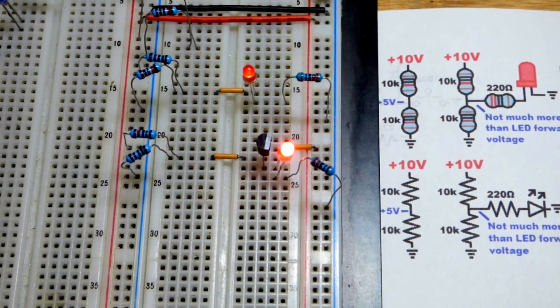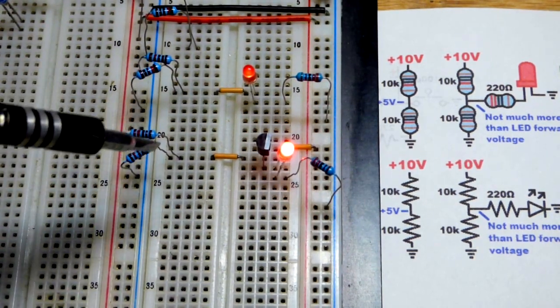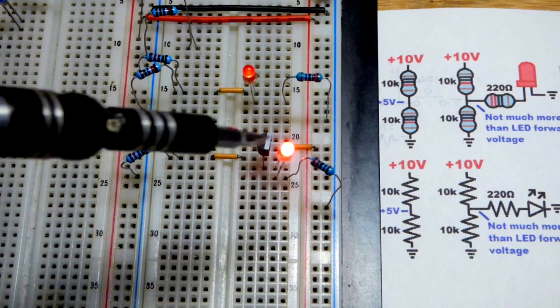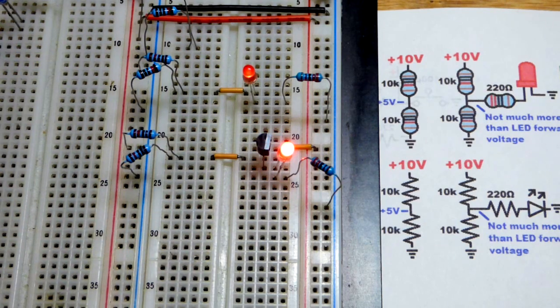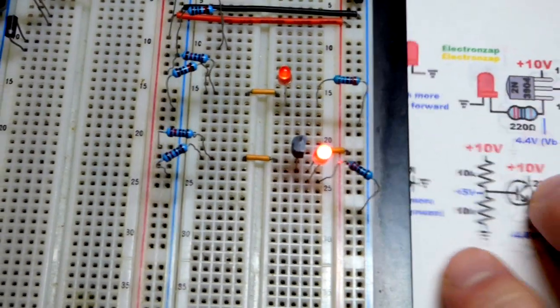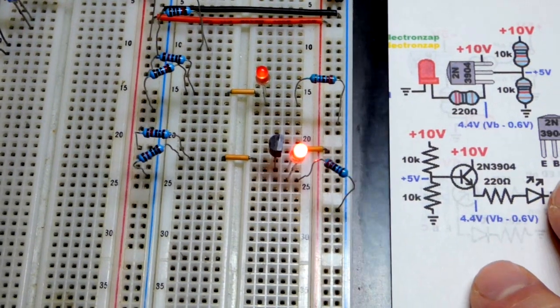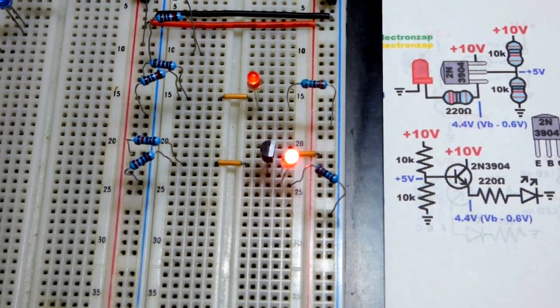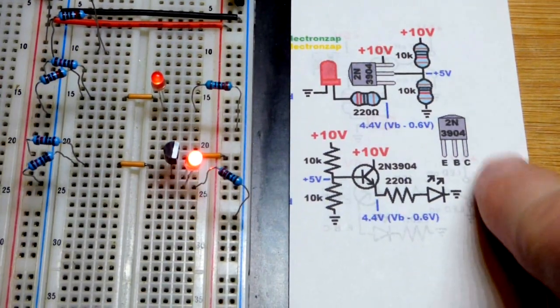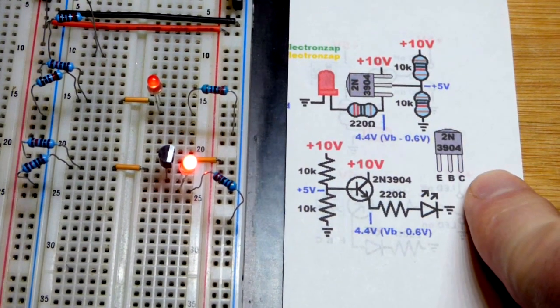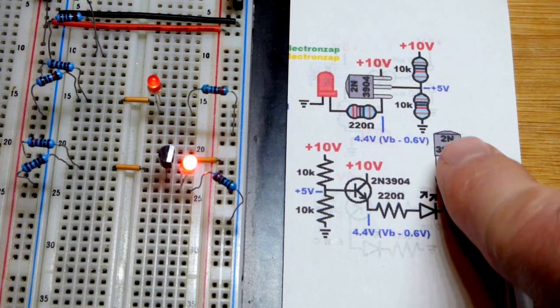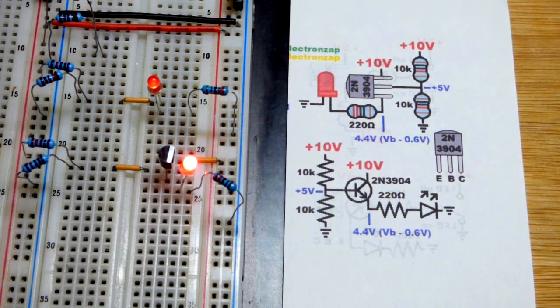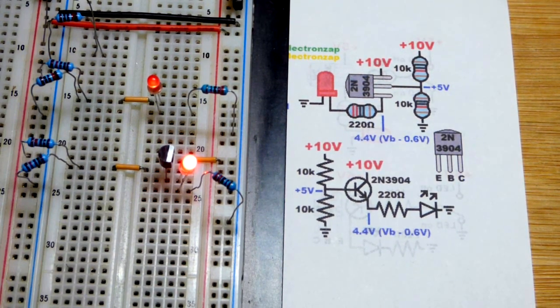So down here we also have the voltage set, and we're using a transistor to transfer the voltage. So now that's not perfect either, but by far better, as you can see right there with the example. So here I have a couple pictorials. We need to make an emitter follower if we're going to use a bipolar junction transistor to transfer a voltage.